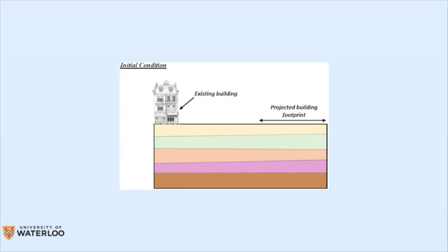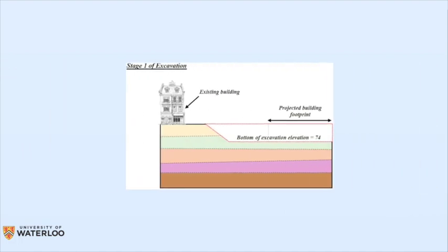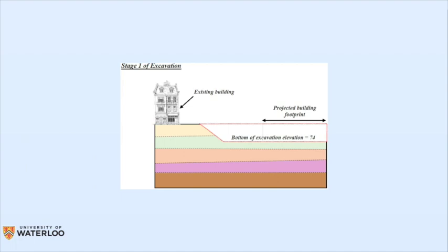The excavation is supposed to be about 12 meters deep, on average, not exactly. Because 12 meters is too much for just one step excavation, the excavation is done in 2 stages. The first one, 6 meters, the second one, another 6 meters. So this is the idea for the first stage of the excavation. Your assignment for the project is basically to define the inclination of this slope. It's not that difficult, but it's challenging in the sense that you have some constraints for the model.